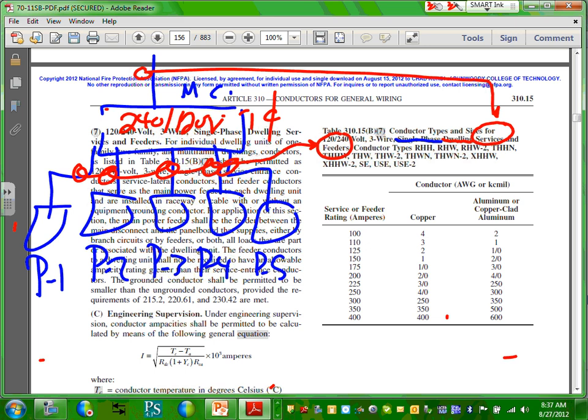Can everybody understand the limitation of this table? Single phase dwelling 120/240. If you're using 208/120, do you see anything 208/120 here? Can you use it for an apartment at 208/120? No. This is a special condition table, a very special condition table. Okay, so let's go size.